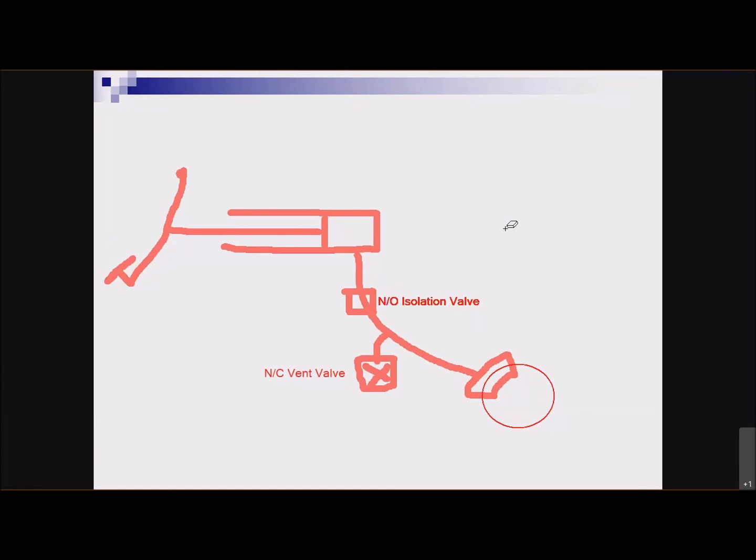So let's just stick with one wheel, all right? Just one wheel is locking up. We'll say the right front wheel is locking up. So the computer knows this because that right front wheel speed sensor decelerates a lot faster, or maybe even goes right to 0. So what's the first step? Okay, all right, that wheel is locking up. We need to stop increasing the pressure to that caliper. So let's close this normally open isolation valve.